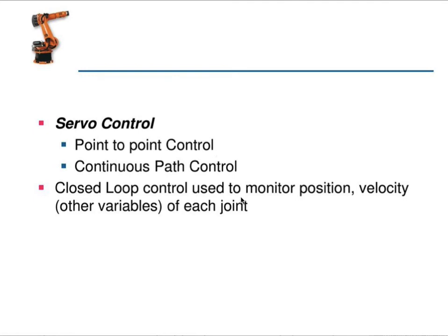And if you see in continuous path control, the servo control is used to maintain continuous control over the position and speed of the manipulator. A playback robot with continuous path control has the inherent capacity for PTP control as well. In a continuous path motion, the movement of the arm and wrist is controlled during the motion, isn't it? This is what we are talking about, the controllers.